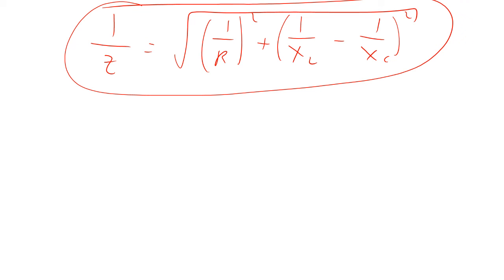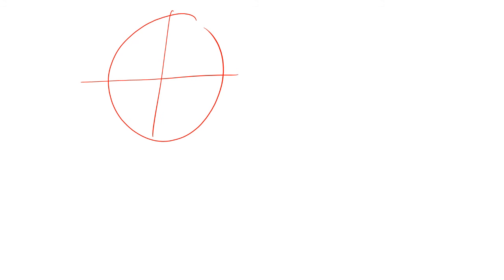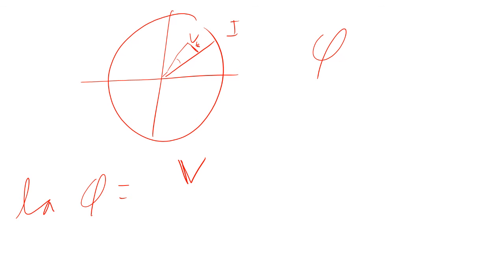Notice also that as we did this, for the series circuit, once again we had I here, but the total voltage was right there. So there's a difference in there. There's a phase angle. So this right here is going to be V, so the tangent of the phase angle is going to be VL minus VC divided by VR, which was that right there.